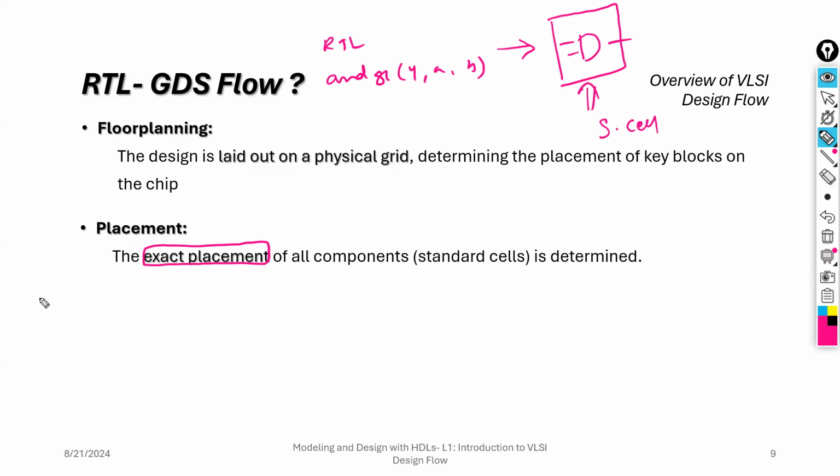So this standard cell we will place in an IC. In the previous floor planning stage, we can see there are different kinds of grids, right? So we can take that particular gate as a standard cell and place it in a grid. Wherever it is possible, it will be placed there. That is the responsibility of the placement tool. The majority of the things are automatic. We just have to give some instructions, and the tool will perform this automatically. We cannot do the placing of the cells manually. Is this point clear?